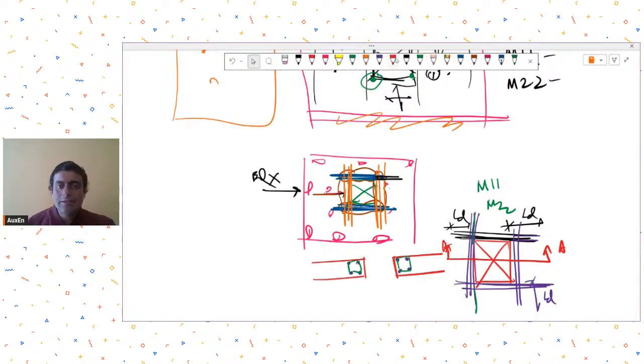In some cases, if you refer to SP34, it further asks you to add a diagonal reinforcement also around the corners, so that the corner stresses are taken better care of. So this is another arrangement that your SP34 suggests around the openings. Okay. So these were my thoughts about reinforcement detailing around the openings.